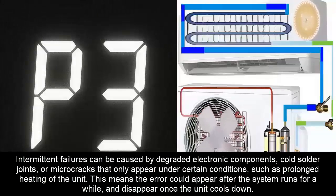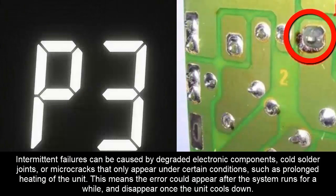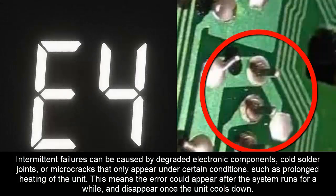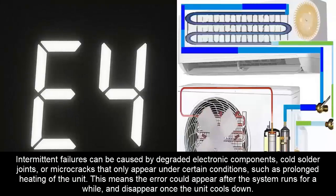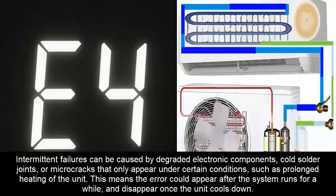Intermittent failures can be caused by degraded electronic components, cold solder joints, or micro cracks that only appear under certain conditions, such as prolonged heating of the unit. This means the error could appear after the system runs for a while, and disappear once the unit cools down.